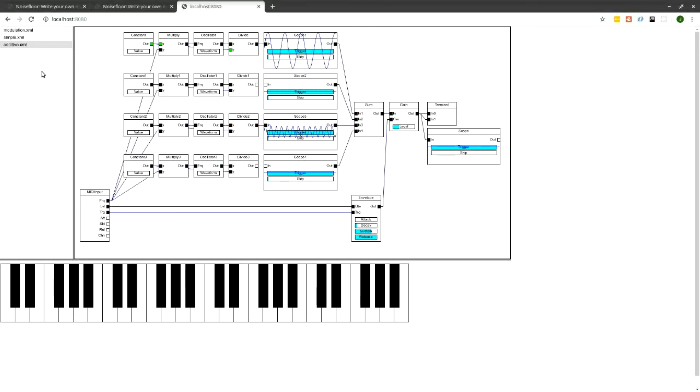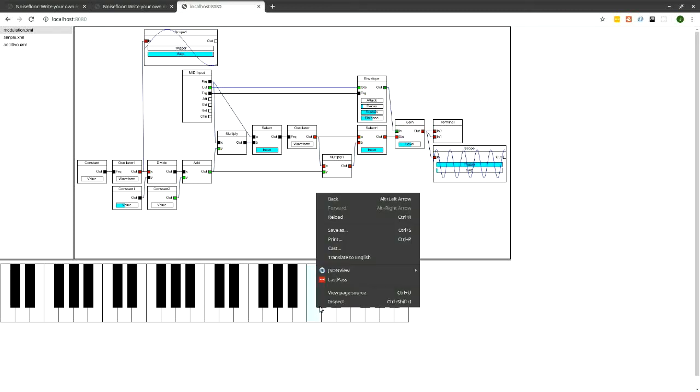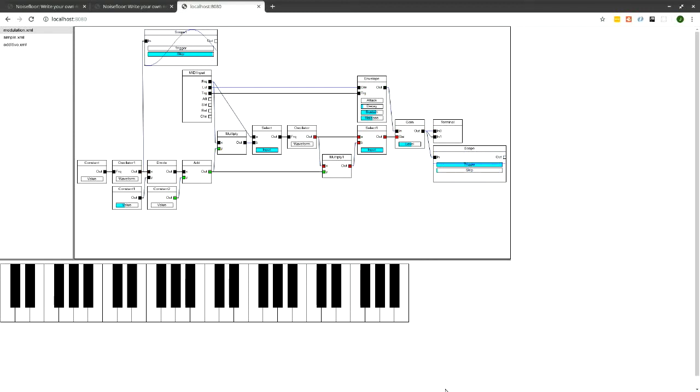Moving into some modulation techniques. This one's a bit of a behemoth because it does both amplitude and frequency modulation at the same time. Here we've got the concept of what we call a low frequency oscillator, which is a periodic waveform operating in ranges normally below the audible, but can be used as a control to modulate the wave. So in this configuration it's set for frequency modulation, so if we hit that key, we can see that wave on the right is then swaying in and out in a kind of vibrato effect.